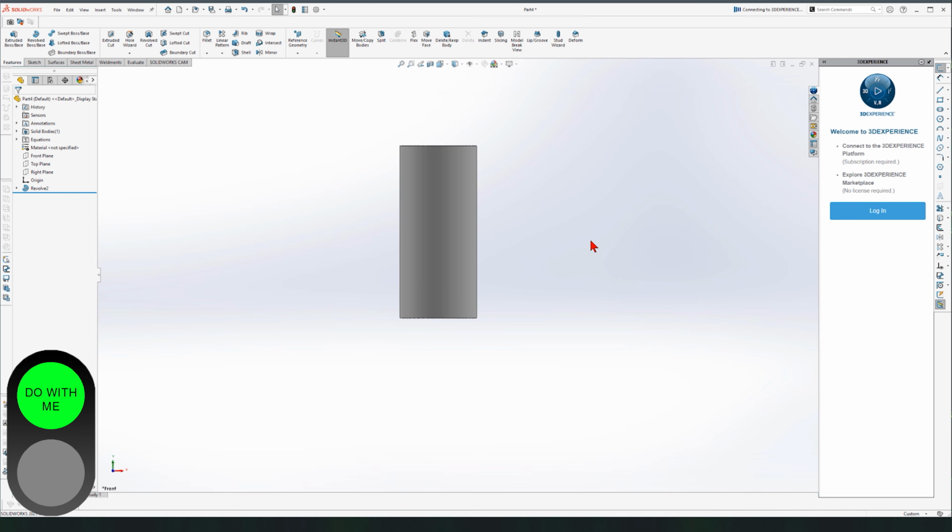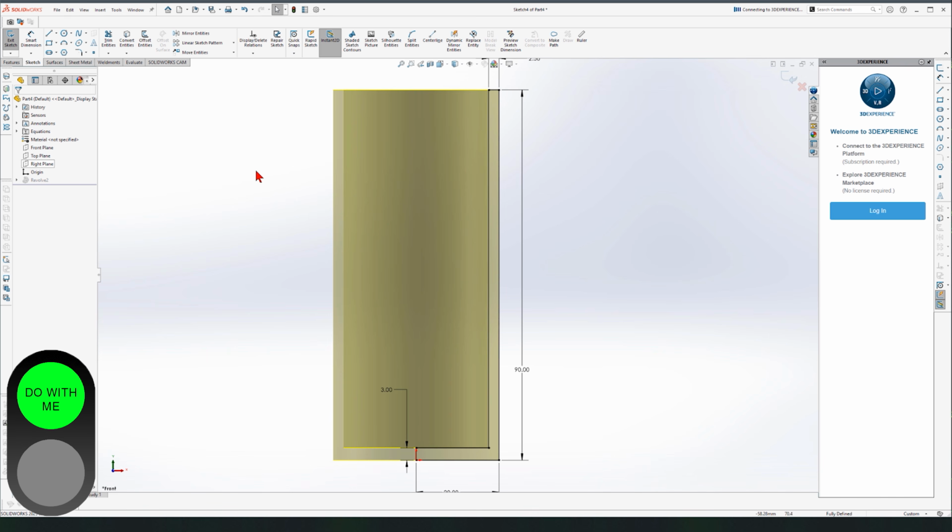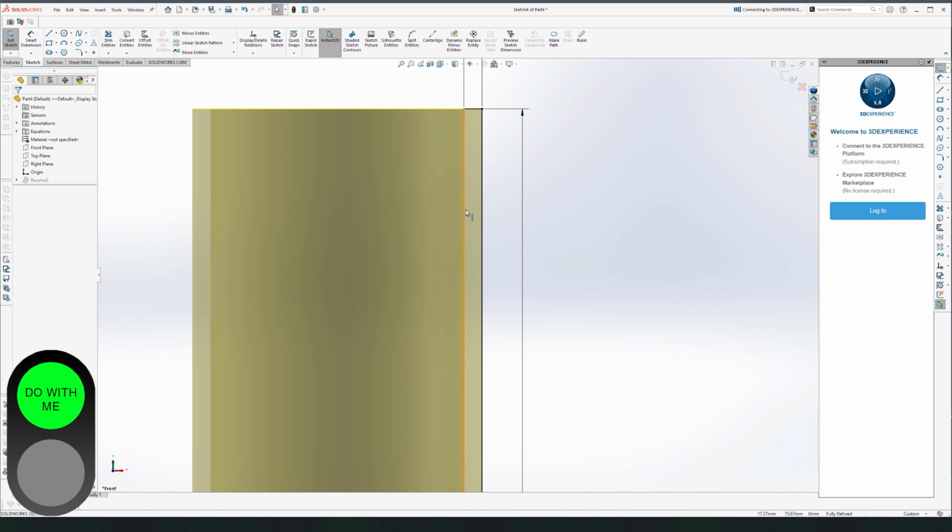and click OK. Better. Again, click on Revolve, Edit Sketch, and let's add this belt over here. We want to pick 3-point arc. If you don't see it here, click on this arrow on the center tool, and among these options, pick 3-point arc.